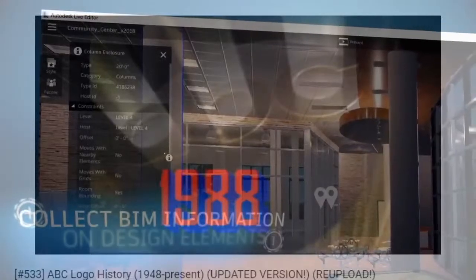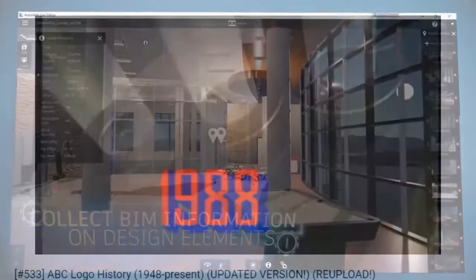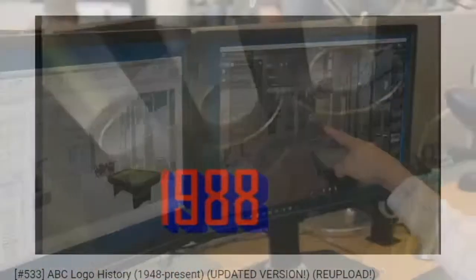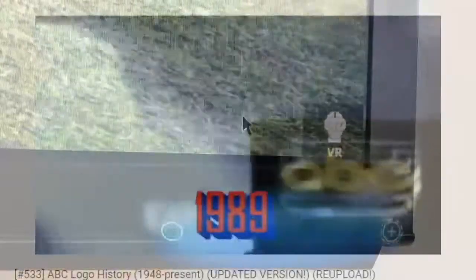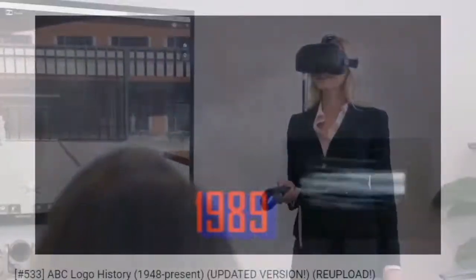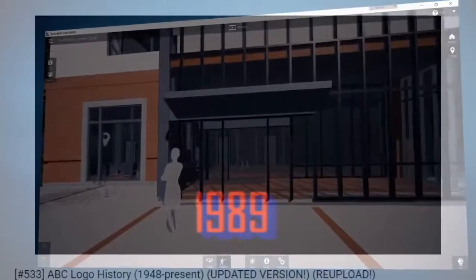You have to select it, and then you have to go up top. You have to leave the dialog box. You have to keep it highlighted, and you go to it, and you select it. I forgot that. All right. It doesn't really tell you that. In level 1 floor plan, click near the edge of the split face you created earlier to assign the material. It's not like you're loaded into the material paint tool, close the dialog box, and then select. You do it within the context of opening the dialog box.